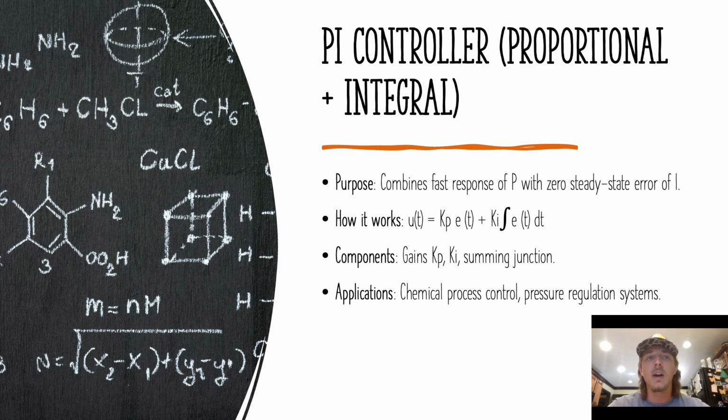This makes the PI controller ideal for many practical control applications where noise is present or where the derivative term might cause instability. PI controllers are very simple. They're simpler to implement and tune compared to full PID controllers, while still offering reliable performance in steady-state and transient conditions. PI controllers are used widely in industries such as chemical processing, HVAC, motor speed regulation, and liquid level control, where precision and stability are most important.